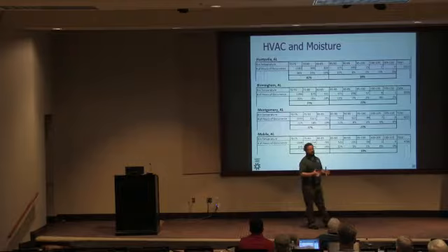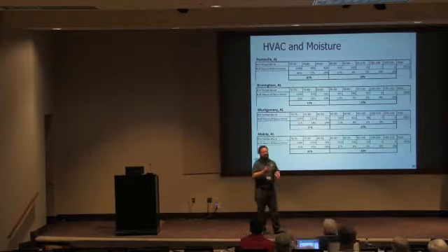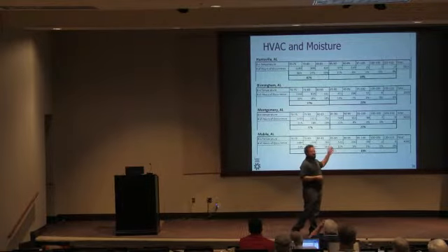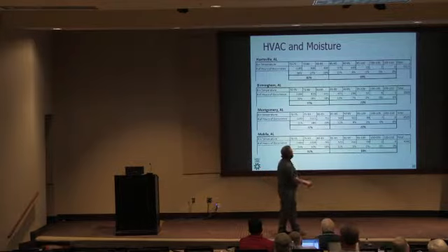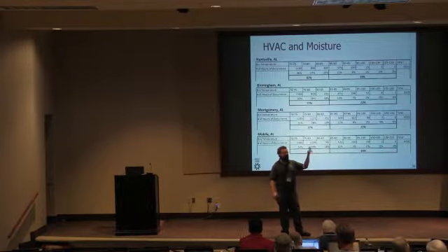What fixes all of this is multi-stage equipment, which is what is coming into our industry, which allows you to have a blower that can move the air at different speeds. It's more energy efficient, it provides better comfort, and basically allows you to oversize the equipment so that if it's 95 degrees outside and they're having a pool party and they have the sliding glass door open and they're running the air conditioning system, well, okay, we can actually handle that load because we're way oversized.